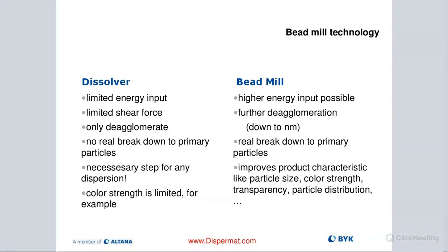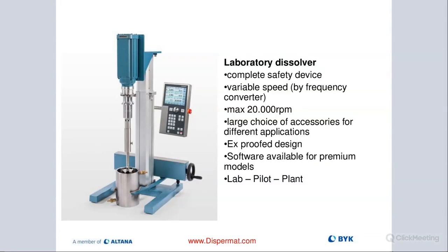With that, we can put in a lot more energy. It allows us to go down to the primary particle size, down to sub 100 nanometers, not unusual, especially for these new end-use markets. So even automotive coatings require really, really fine pigments, a small particle size, that makes these automotive coatings really pop and give them a really strong and beautiful appearance, because they are milled really well. So that's critical to remember, the difference between dispersing and what's actually happening when we are milling.